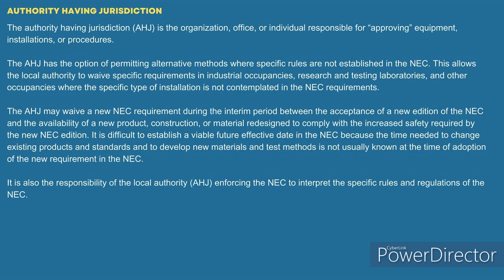Okay. Yeah, and this brings up my whole point. I installed an EVSE charger at a personal friend of mine's house, and I asked if they wanted it on GFCI, and they were like, no, it says right here it already has GFCI in it. The only thing I had to do was hardwire it, and then I went to the AHJ, to the inspector, and I said, here are the listed and labeled manufacturer instructions that say it just needs to be hardwired to a 50 amp breaker and we're good to go, right?